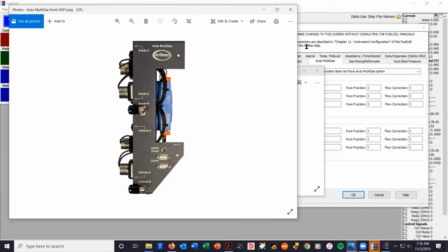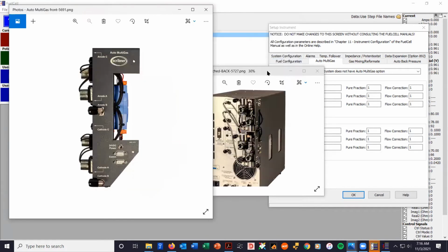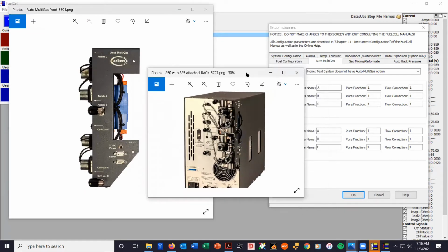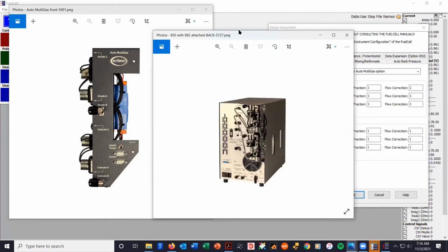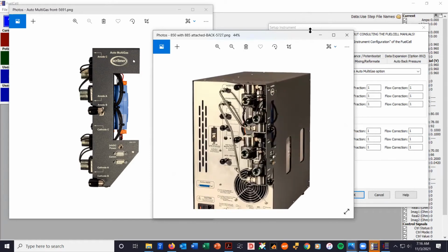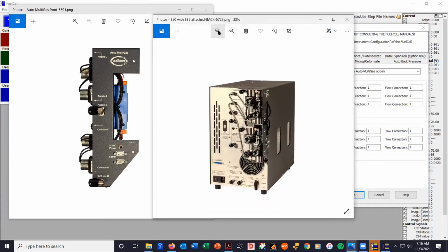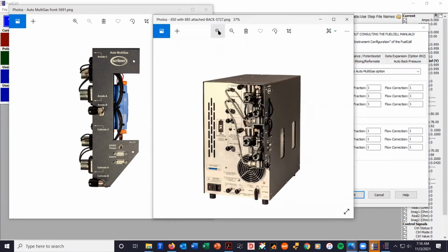A very common thing to do in fuel cell testing, at least within PEM testing, is to switch between, say, hydrogen on the anode, and on the cathode switch between air and oxygen, for example, testing with pure oxygen versus testing with air, but also running with nitrogen on the cathode for certain diagnostics. And so instead of having to connect and disconnect your nitrogen supply to your cathode inlet, we can automatically switch between those gases by having air, nitrogen, and oxygen all connected to the cathode, as an example.